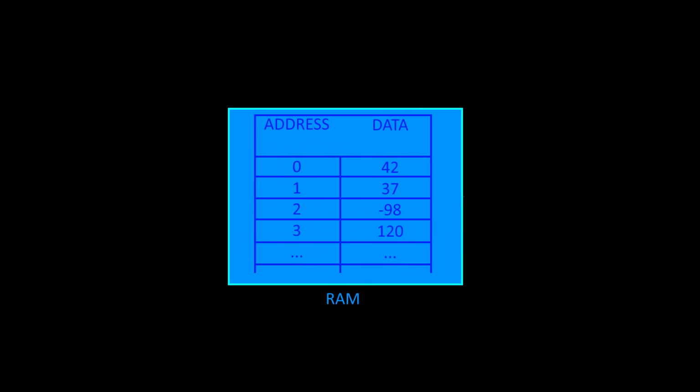To understand how RAM works, we can think of the memory space as being divided up into several cells, each of which can store a number. Each cell in memory is given a specific address. In order to access or modify a value in memory, we need to give the RAM unit an address as input. We also need to give a read input and a write input so that we can tell RAM whether we are reading or writing data to or from that memory cell. Finally, we will have some data input-output lines. These lines will be used to both read data from memory and to write data to memory.